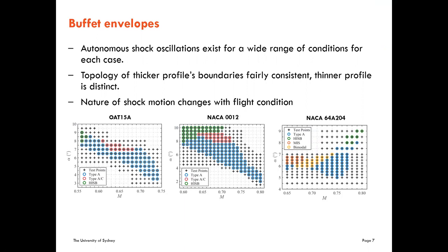Yeah, so I have 2 final questions. You have reported, I think on page 9 or 14, the Kelvin-Helmholtz instability and von Karman shedding in transonic buffet. I haven't found any literature on transonic buffet from the aeroelasticity point of view. So is it your new finding to look into it from these Kelvin-Helmholtz instabilities and von Karman shedding? At what Mach number does this kind of thing happen?